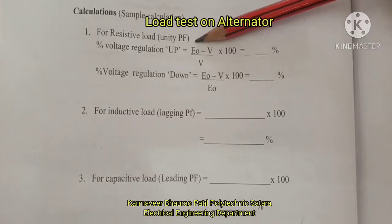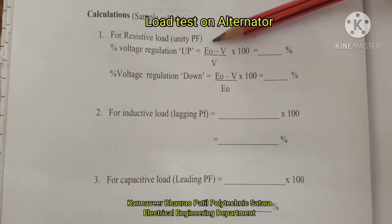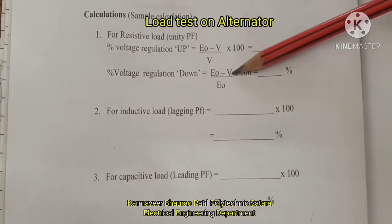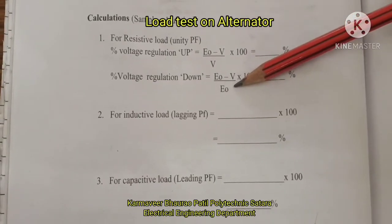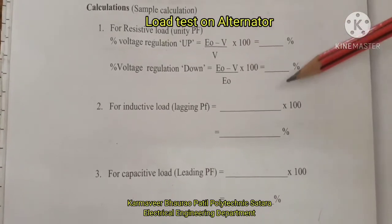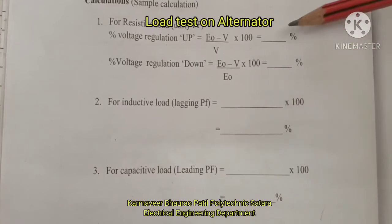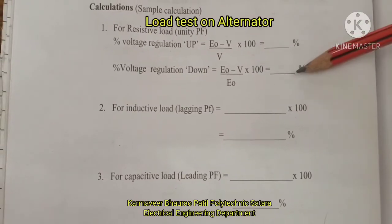The formula is the same: (E0 minus V) upon V is up regulation, or (E0 minus V) upon E0 is down regulation. So you have to calculate up regulation and down regulation for each stage. You take only one reading, and for that reading calculate up and down regulation.